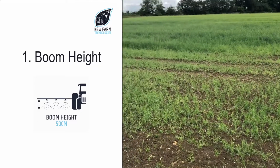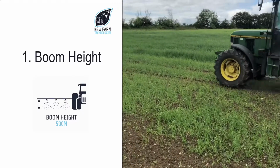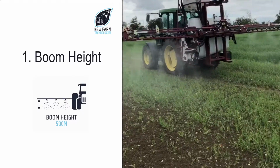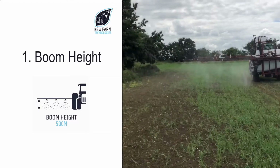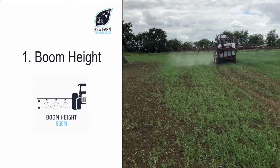Now Tim's going to drive past with the boom at a metre, and remember, a metre of boom height, 10 times more drift. And look here, you can see the drift from the flat fans. Even though the 3D90s are looking very good, there is still an element of drift. But from the flat fans, you can see a dreadful amount of drift. And this is why boom height is so important to maximise product deposition.